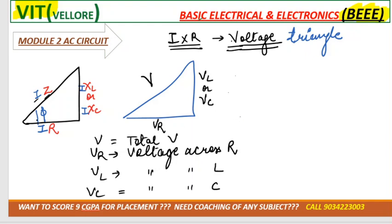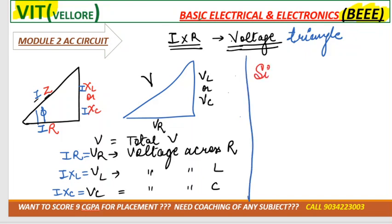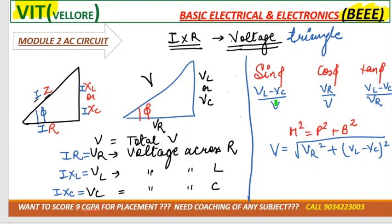Understood? So what we got, the formula: VR is how much? I into R. VL is how much? I into XL. VC is how much? I into XC. Similarly, we can get sin phi, cos phi and tan phi and apply the Pythagoras theorem as we did in the previous case. So sin phi is this one, cos phi is this one, and tan phi is this one. And by applying the Pythagoras theorem, we are getting this formula. Correct?